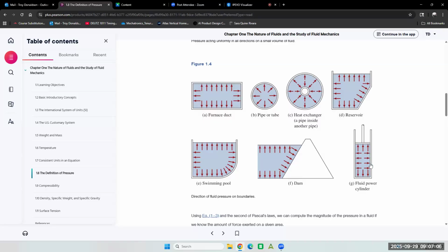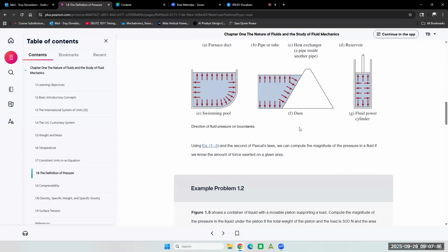When you increase the pressure in here, it'll move this piston and it'll do work for you, whether it's a piece of equipment or a steering system in your car, same kind of thing. Brake system in your car: when you push that pedal, it is pressing on a piston that is pushing hydraulic oil to your brake. When your brakes leak, your brakes don't work so well because it's losing that fluid pressure. So yeah, we'll look at all of those.